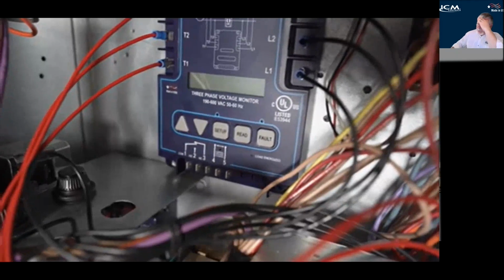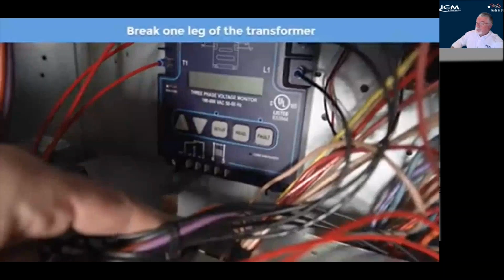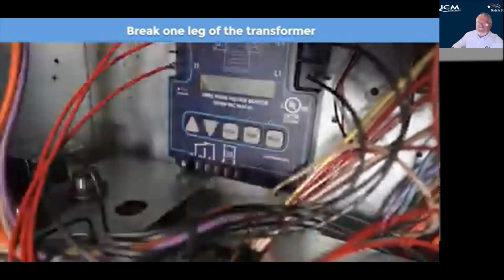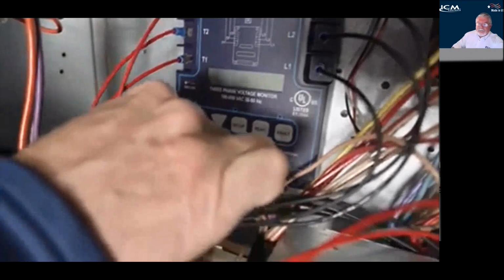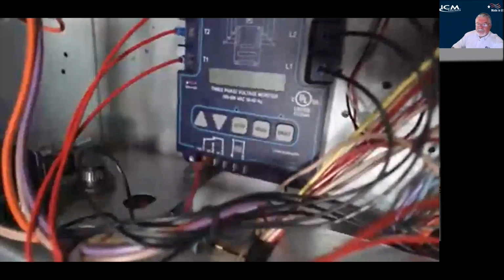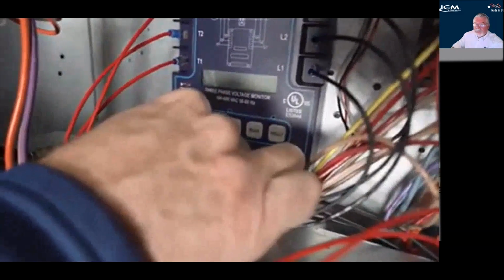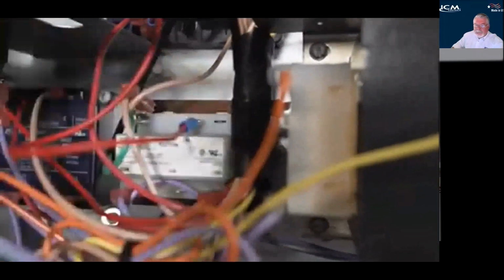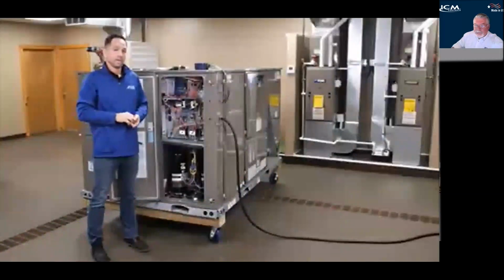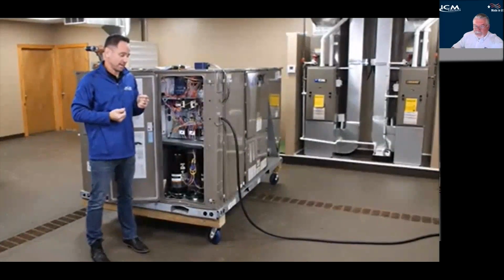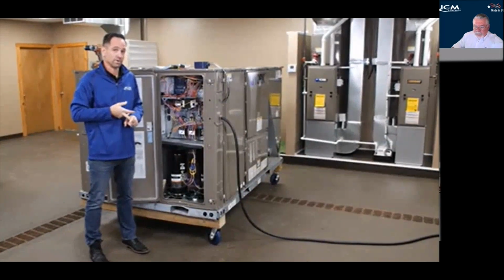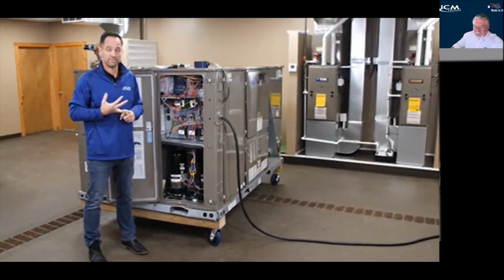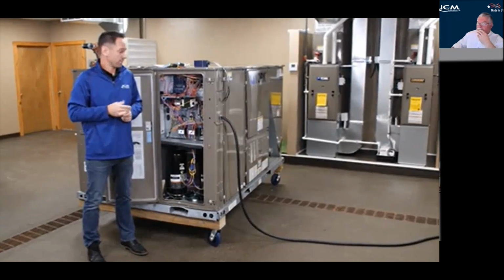So last thing we have to do is take the power off of your transformer, connect it to the common side of the 450A, take a jumper wire from the normally open terminal, and connect it back to the 24 volts on the transformer. So now our unit is completely protected against phase loss, over and under voltage, any line voltage issues we might have from the power grid.